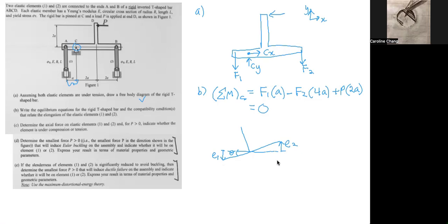That's just an intuitive fact, because as this end is pulled upwards, this other end is going to be compressed because there's this beam over here resisting the force. And over here, this member is pulling on this section, while over here, this member is pushing upwards on that section.